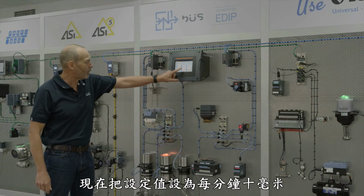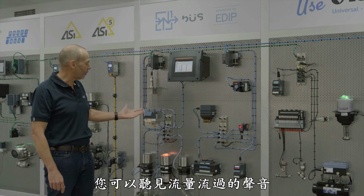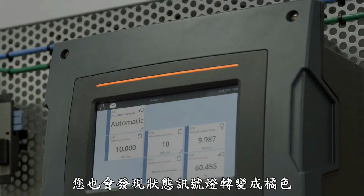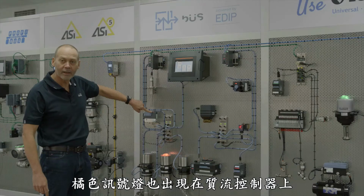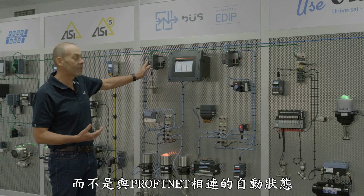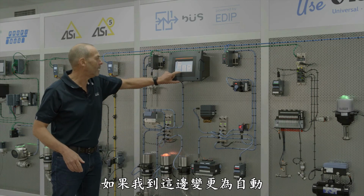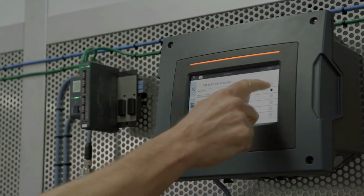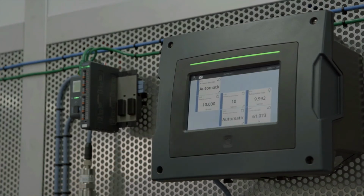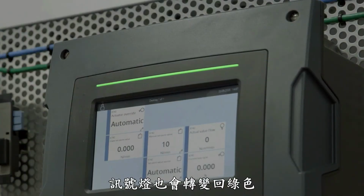I've now set a set point of 10 normal litres per minute, and you can hear the flow flowing through that. You'll notice also the bar here has gone orange because the orange bar is also on the top of the mass flow controller. That's showing that this is actually under manual override, and it's not in automatic connected to the Profinet system. Of course, if I go back and put it back into automatic, it goes back to taking its set point from the main control system, and the bar goes back to green.